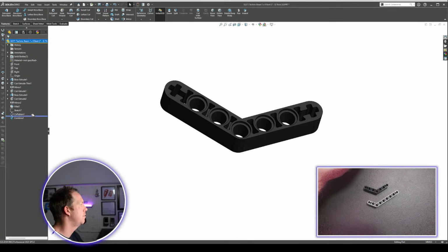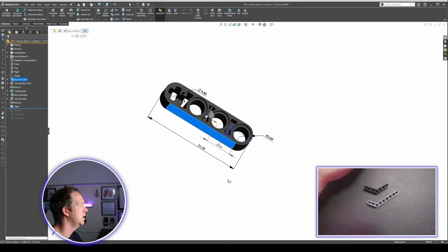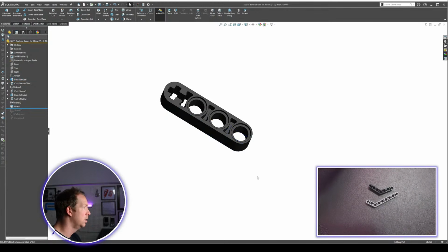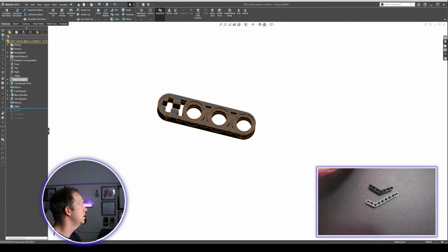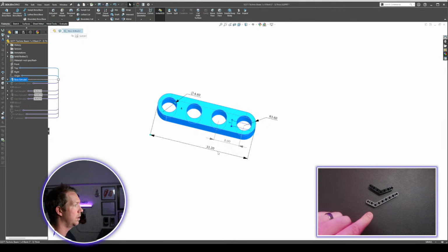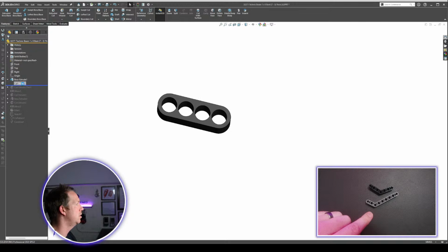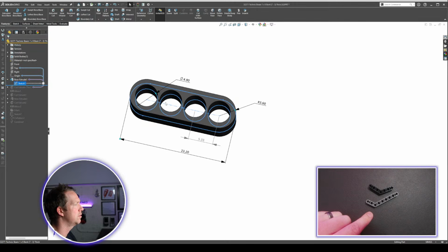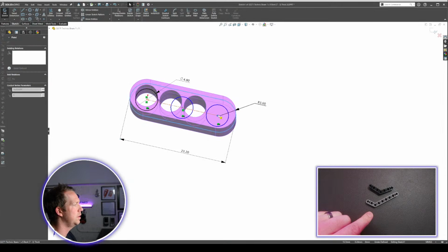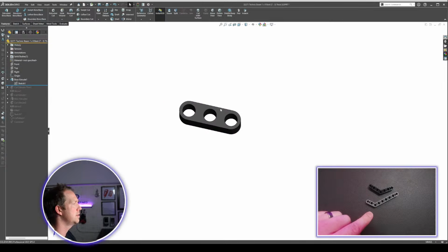So I'm just going to roll back before the combine, and just see what I've got here. Now that length needs to change. All right, so I'm going to edit this feature and bring this all back a step. So the extrude length, because I'm only going to 3, I'm going to reduce that by 8, minus 8. But I'm going to change the whole number. Whole number is going to change to 3. And I need to update then this last hole to be on this point here. All right, that's the first step.